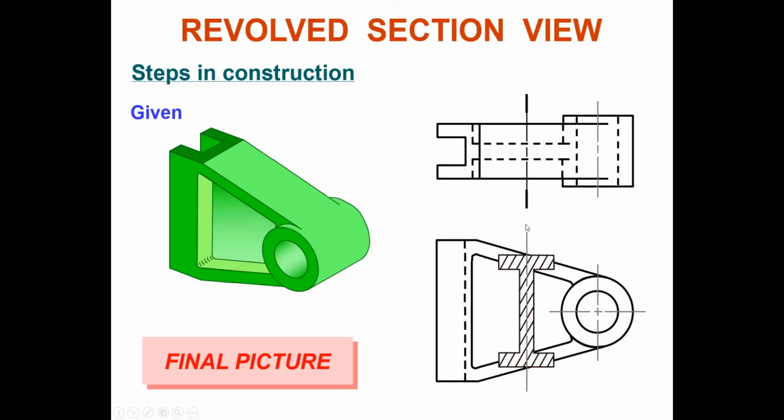Okay. Remember I cakap you, kalau you take class, this is very important class. You need to understand it. Full section view, of course, any hidden line on the view where you do sectioning, front view where you have section line, any hidden line, remove. Remember for full section. Even for half section, the view, like in this case, front view, you do sectioning, any hidden line, the rest of the region, no hidden line. Also offset section, no hidden line.